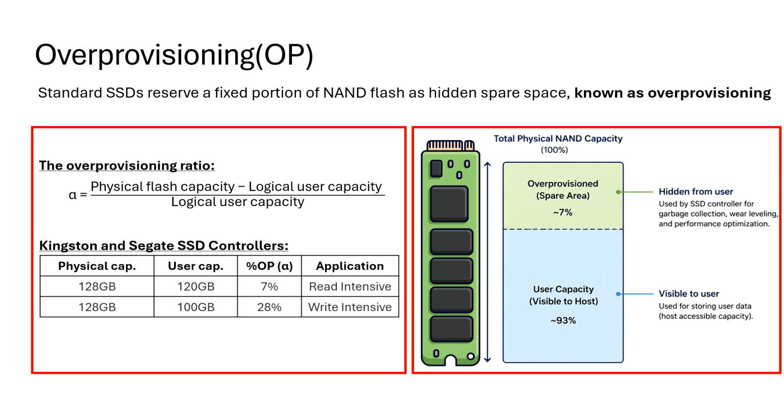There are some data center based SSDs and some enterprise based SSDs. In enterprise, they think mostly about read intensive workloads. In data centers, in some use cases, they think about write intensive workloads, and they raise this over provisioning to lower the write amplification factor, and we will see how that lowers the write amplification factor in the next slide.